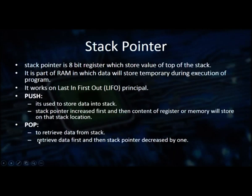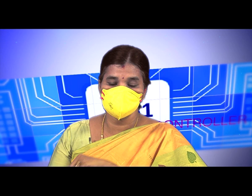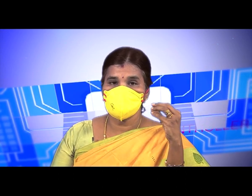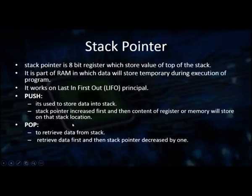During the read operation, it retrieves the data first, then the stack pointer is decreased by 1. First it takes the data, then the address is decreased by 1. Push first increases the address, then writes the data. Pop takes the data, then the address is decreased by 1. That is the difference between push and pop.